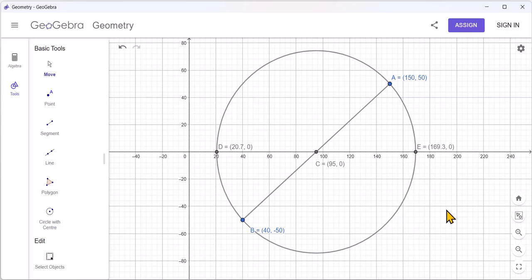So I have a special case because the product of my 2 normal stresses is a positive number. Quickly you will see this. If I want to find the shear stress here, I would draw a line parallel to my tau axis and find the intersect of that line with the circle. That is the orientation that my shear will be maximum, but not in this case.